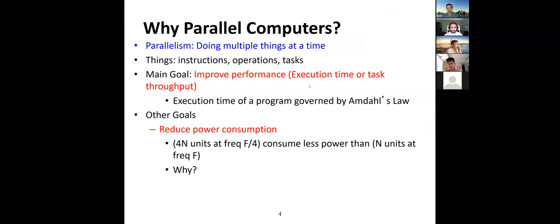Yeah, so I think Behrus, sorry if I mispronounced your name, you're correct. The problem is that if you look at the equations for the power, the frequency there is not linear, it's actually at least quadratic, right? So if I reduce the frequency by a quarter, I would actually reduce the power by 1/16, right?